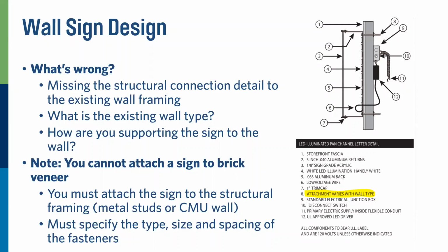These signs are designed for the same wind speed. Put in perspective, a 100-plus mile an hour wind is probably going to be around 50 pounds per square foot for components and cladding.